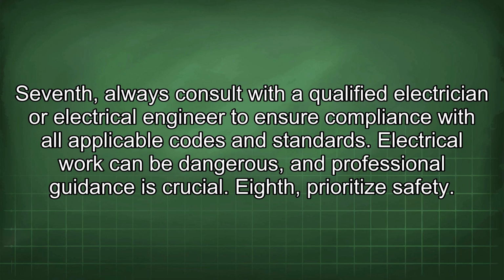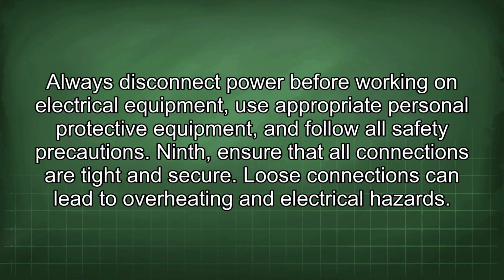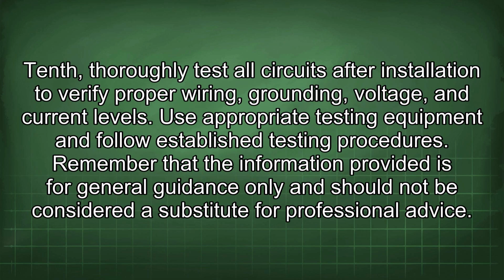Eighth, prioritize safety. Always disconnect power before working on electrical equipment, use appropriate personal protective equipment, and follow all safety precautions. Ninth, ensure that all connections are tight and secure. Loose connections can lead to overheating and electrical hazards. Tenth, thoroughly test all circuits after installation to verify proper wiring, grounding, voltage, and current levels. Use appropriate testing equipment and follow established testing procedures.